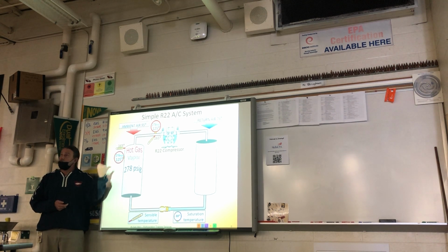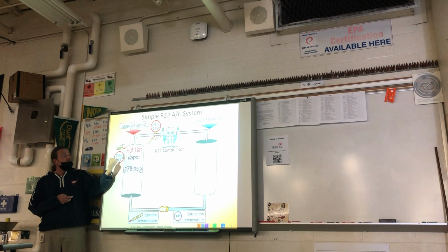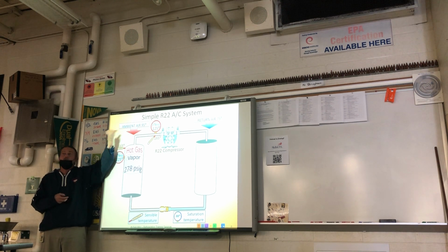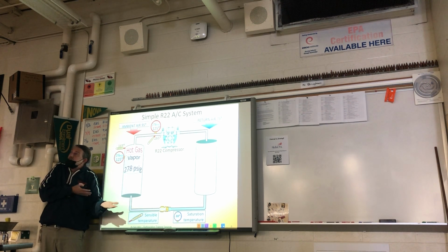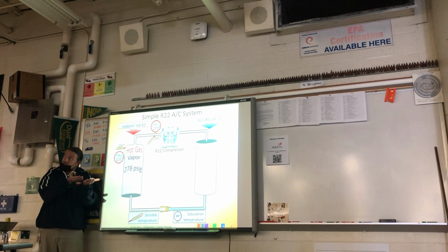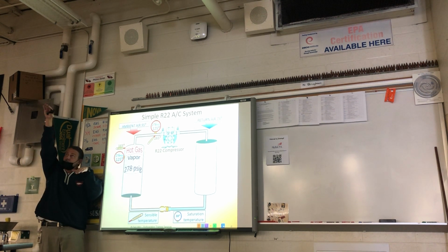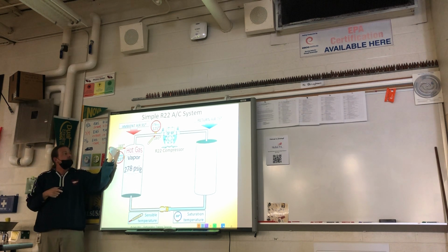And that was what my condenser crew told me. You said three things that it was going through. First thing was to get it down to the temperature of 125 degrees. So it's got to remove heat, right? And because the air is 95 degrees, the heat flows from warmer to cooler, that basic law of thermodynamics, the second one. 95 is cool compared to 125. So when we have a temperature difference, you're going to have that transfer of heat naturally occur. And that's what we want.